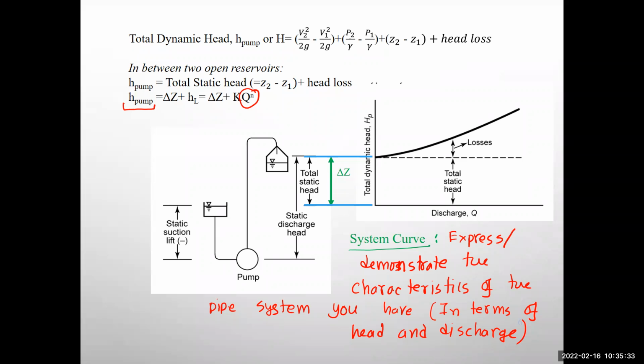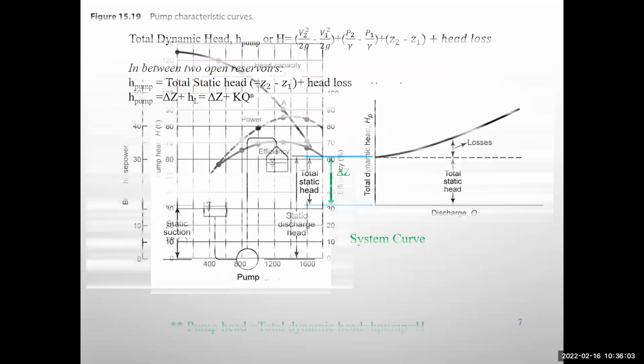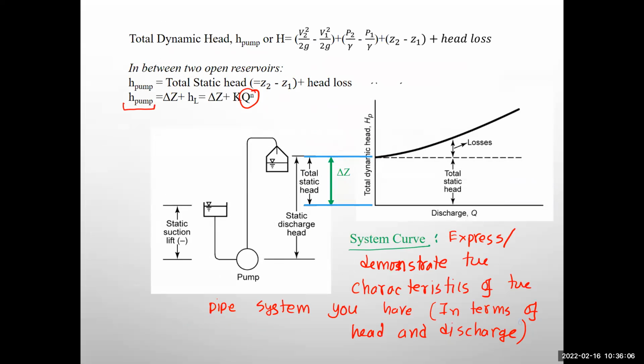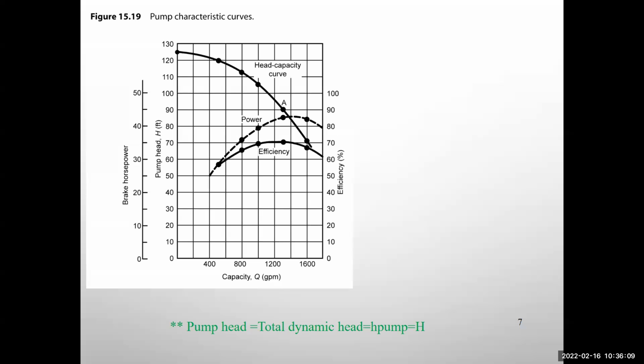The pump itself, right? I don't know if you have any experience of buying a pump, but just think about any electronics: whenever you buy something, there is a user manual. So whenever you buy a pump, there will be a user manual. At the same time, there will be a curve which will give you at which head what discharge you should expect. That characteristic is the pump characteristics curve. So the pump characteristics, I think you already have that in your copy, the definition.